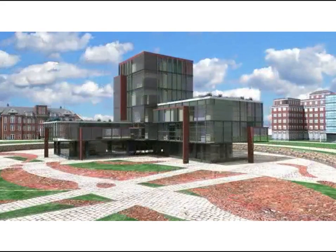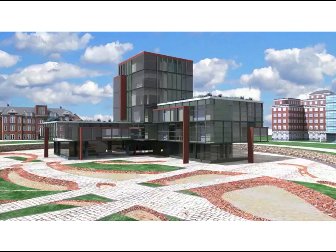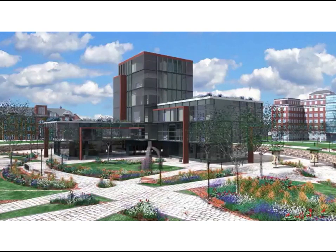The third system is called bioretention and is also known as a rain garden. A rain garden is a swale or channel that absorbs, holds, and slowly releases excess water. A rain garden section is composed of compacted soils defining the depth, width, and slope of the swale, sand and drainage materials, plant soils, and vegetation native to the region. Rain gardens are not only aesthetically pleasing, they also restore wildlife habitat.